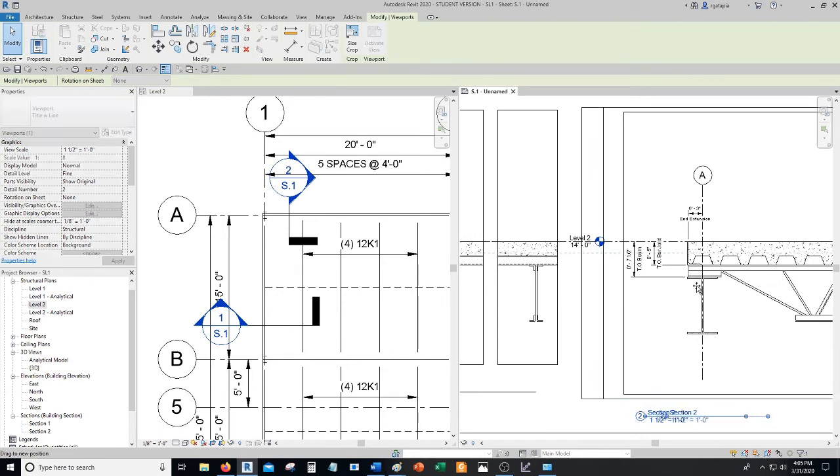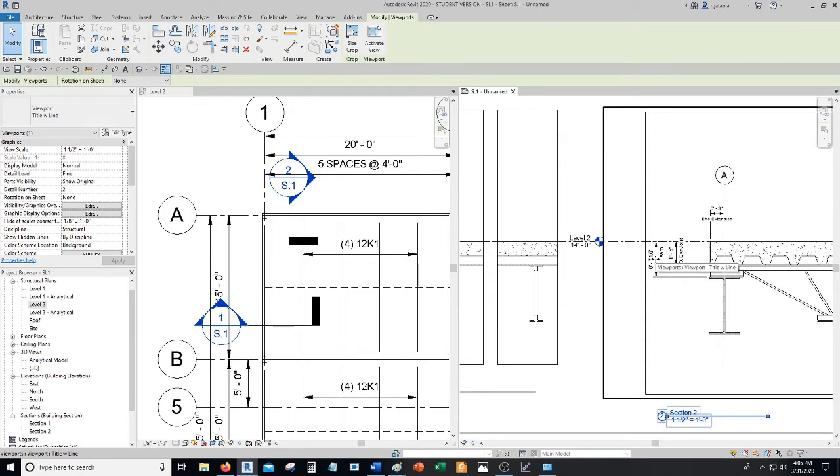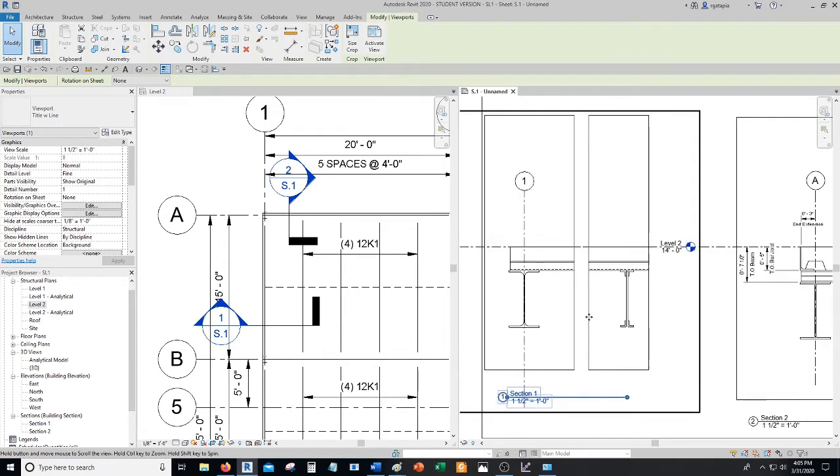And so when we lay the beam that's going east-west, we want the top of it to be 7.5 inches below the finished floor elevation. And for the beams going in the north-south direction, because we want the top of it at the same elevation as the bar joist, that is only 5 inches below the finished floor elevation.